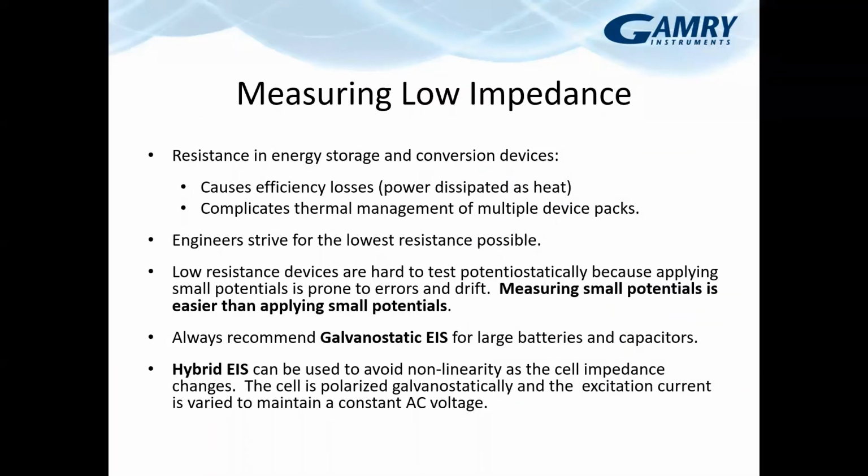For low impedance measurements, again, energy storage and conversion devices are the most common systems that we see that do have low impedance values. The ESR, equivalent series resistance, causes efficiency loss. Power gets dissipated as heat. And when you're assembling multiple packs together, this can lead to thermal management issues for full battery packs.